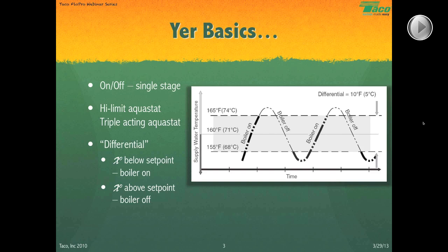Essentially, what happens is when the boiler fires, it keeps burning until the internal temperature of the boiler goes beyond the 160 set point in this example. And it keeps burning until it reaches a temperature 5 degrees above that set point, in this case 165. At that 165 degree temperature, the boiler shuts off. And as you can see, the boiler temperature crests just a little and then it starts to drop. The temperature drops below the set point of 160. It doesn't turn on then. It instead kicks on when the boiler temperature reaches 155 degrees. And then the whole cycle starts again.